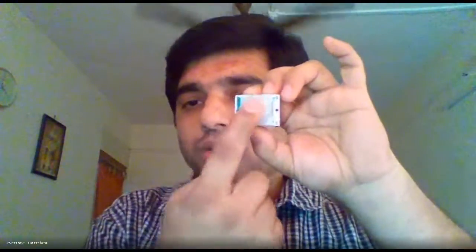We want to halt or control the power supply depending upon the situation we are creating. The situation will be like, we'll have this PIR sensor. Once the activity is detected, only then is the PIR going to trigger. Once the PIR pin is high, meaning the PIR pin is activated, only then does this relay need to be activated, meaning this relay needs to be on, and whatever appliance is connected needs to be turned on or off. So you can make the setting according to you.